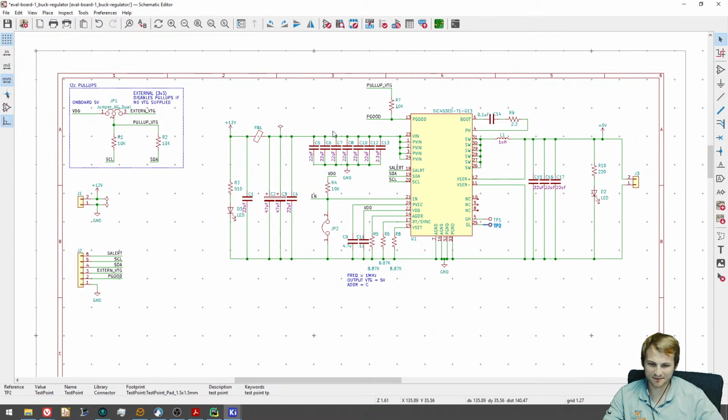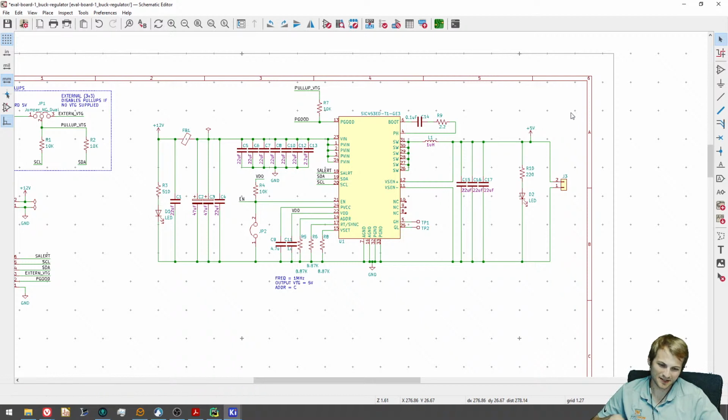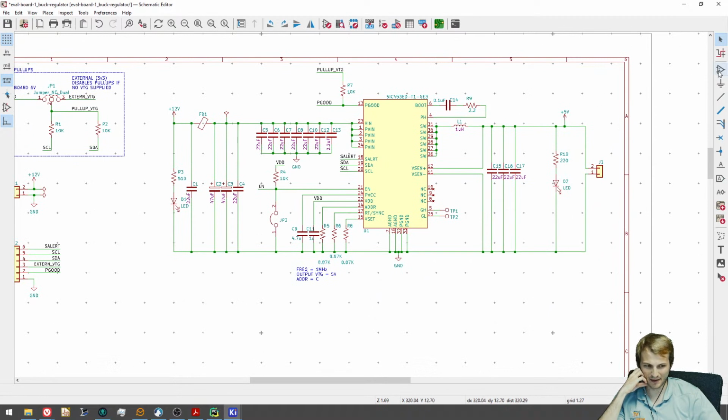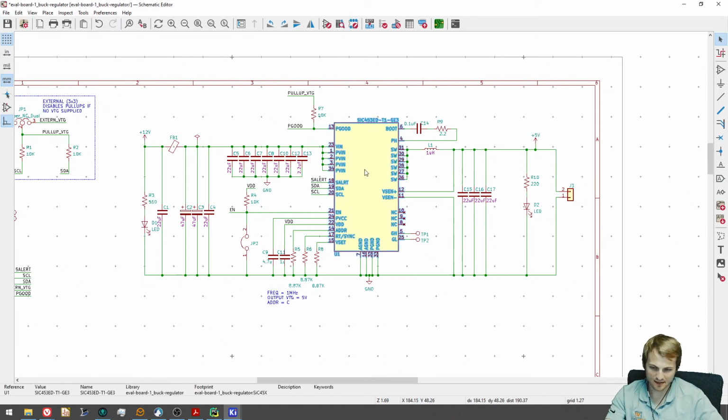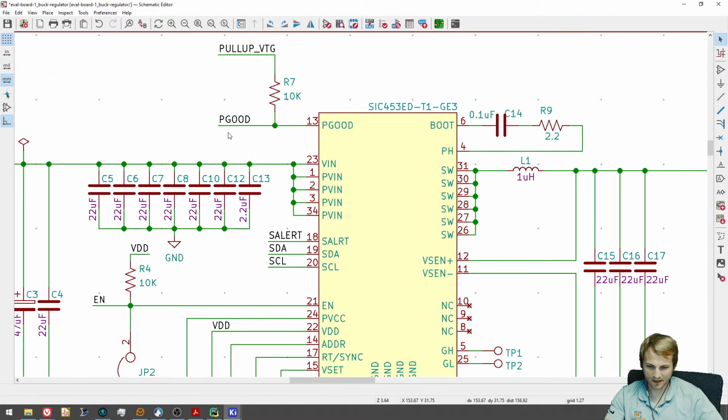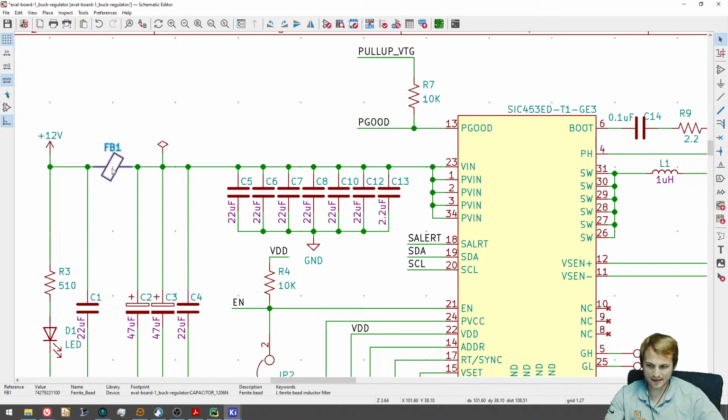Yes. So that's a really good question. That's something that I am absolutely going to be doing in an EMC video. It's something that a lot of data sheets and hardware notes will suggest, especially I believe Atmel, which is now Microchip, for all the Atmega series. They were really bad at always suggesting it. So what Patrick is essentially saying is, let's say this was a microcontroller and this was the input supply. They would recommend having a ferrite on the input to it.